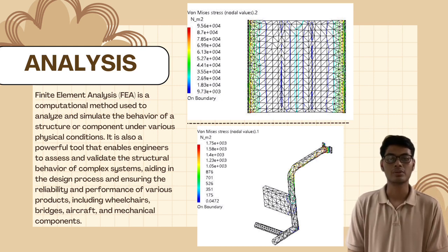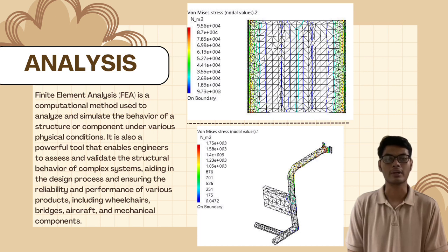First, I will go through the seat. The material that has been chosen for this part is plastic. Then, boundary conditions are clamped at the end of the part, and the distributed load given is 1000 Newton. According to the result of the analysis, it shows that element quality for the criterion stretch is 100% in good condition, while for the aspect ratio, 97.88% is in good quality and only 2.12% is in poor quality.